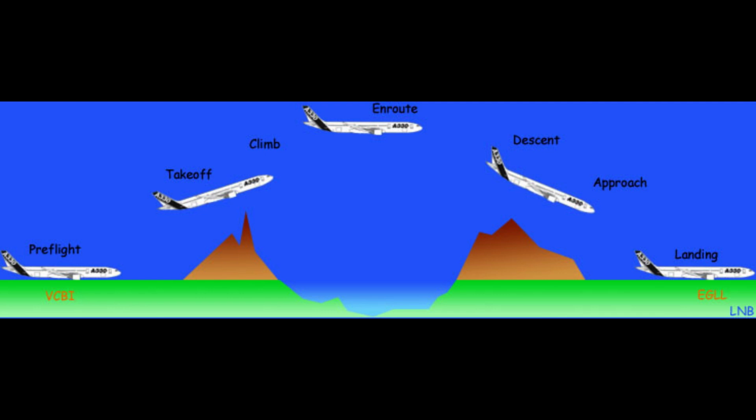Speed and altitude restrictions in clearances are subject to misinterpretation, as evidenced in this case where a corporate flight crew treated instructions in a published procedure as a clearance. The aircraft was at FL 310 and had already programmed the expected crossing altitude of 17,000 feet at the VOR. When the altitude alerter sounded, the pilot advised center that we were leaving FL 310. ATC acknowledged with a Roger.